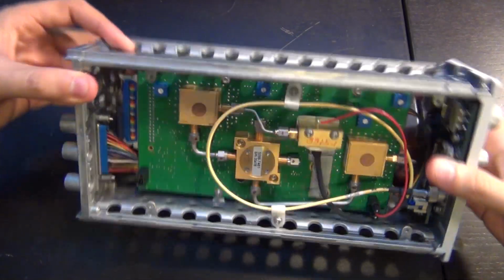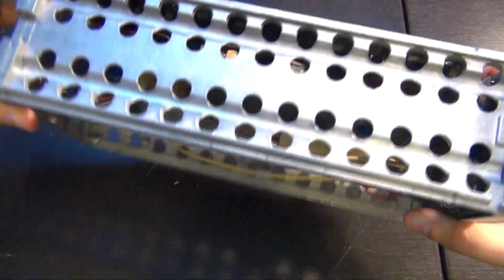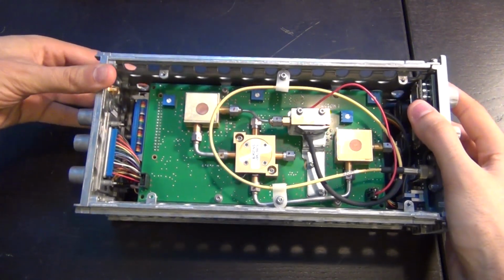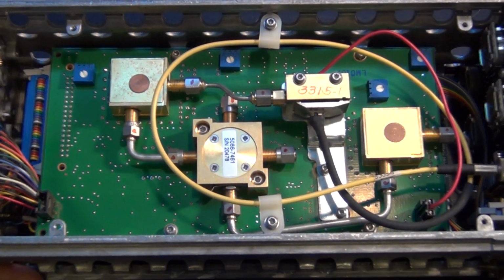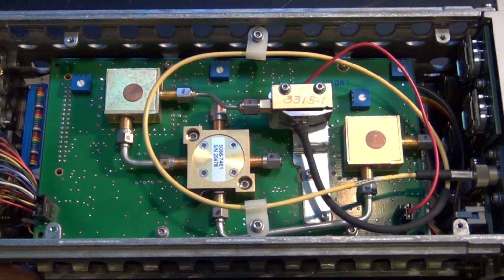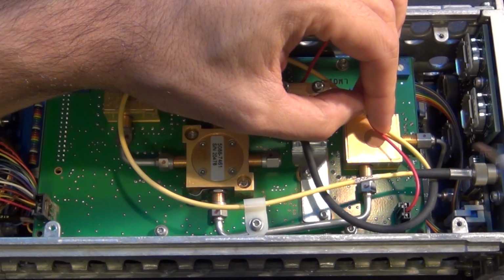So let me show you the other side. On this side, we have nothing more than just a PCB with a bunch of passives, and the exciting stuff is all over here. So let's take a look, and based on what we've just gone over, we should be able to reason out exactly what it is that we're looking for. So let's follow the signal path, pun intended again. So here at the very top, we have our optical input. So the light comes through here, which is modulated, and underneath it, right down in there, is the 50 gigahertz analog input.